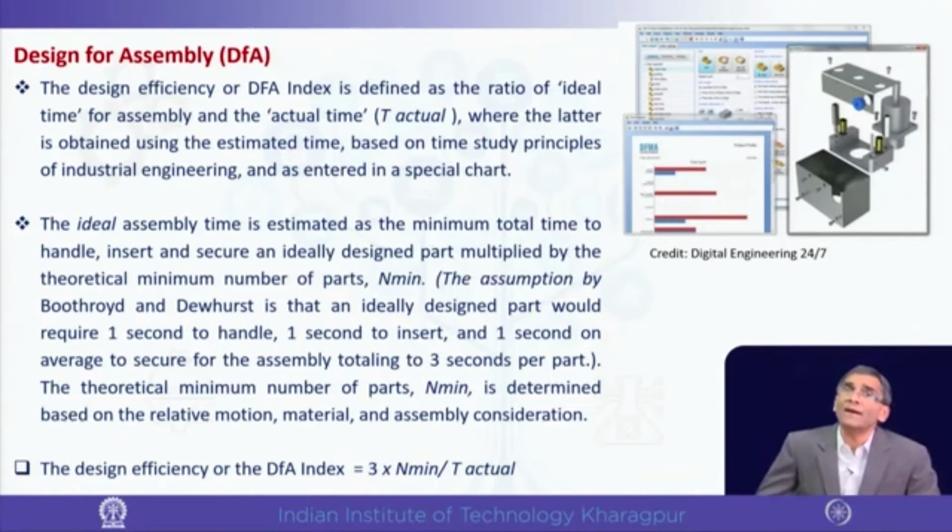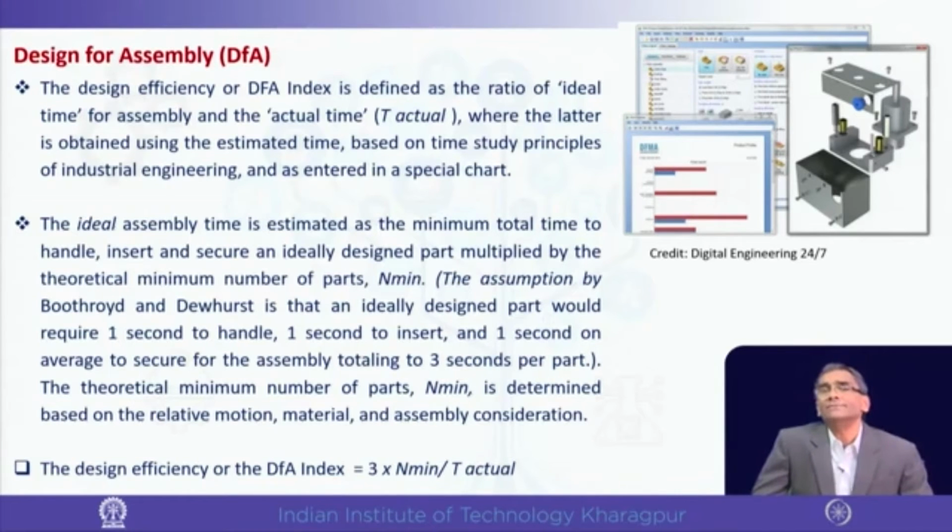There are methods of estimation, which I am not going into, but there are also charts. From there one can find out, or try with similar components to check whether the time coming out is acceptable. A chart has to be established for that particular operation. Based on that chart with the estimated times, the actual time is derived by adding all the individual assembly times.